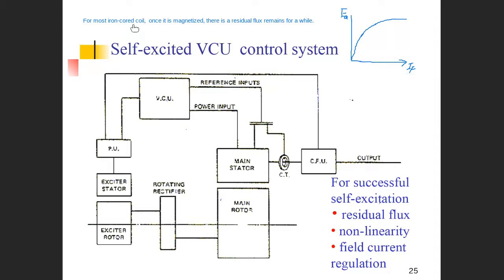So in such a way, even though the magnetic field is weak, when there is rotation, the coils are cutting the residual flux. For a given generator, if there is residual magnetic flux there, once the motor is driven, once an engine drives the mover, there is rotation against the residual flux. There is flux cutting movement. There is induced voltage internally. This induced voltage is probably smaller, but always there.